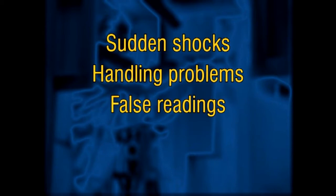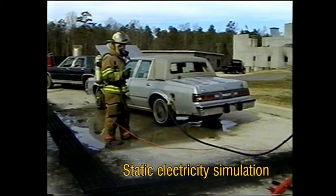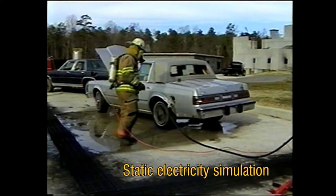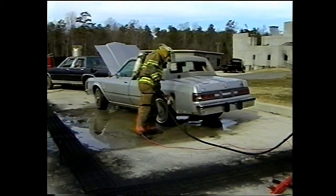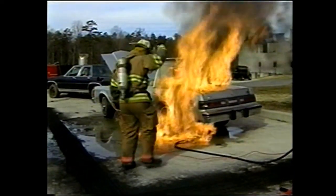There are a number of potential hazards associated with static electricity in the workplace, including sudden unexpected shocks that can lead to involuntary muscle contractions and reflex actions, handling problems resulting from unwanted adhesion or repulsion of materials, false readings in electronic devices, and damage to electronic circuitry. But by far the most serious hazard associated with static electricity is the potential for it to be a source of ignition for fires and explosions. In the vicinity of flammable vapors, gases, powders or dusts, a single static spark can have devastating consequences.